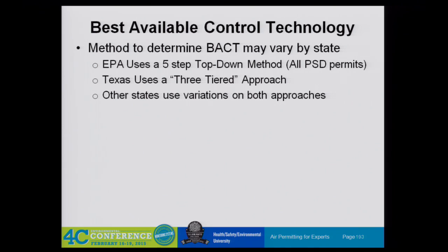That's encroached over the years. I called the state and they were like, well, we understand that if you have certain thermal requirements that result in you running it at higher temperatures than its normal rate of operation, you just call that a thermal factor that's on top of your low NOx rating of 0.06, and it'll account for that additional. So that's where the NOx condition, they make a special...